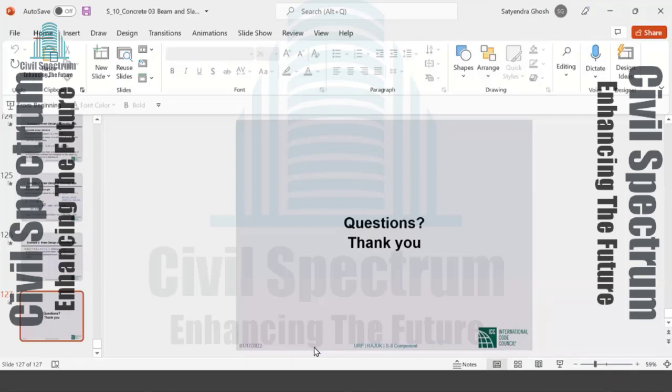Thank you, Dr. Ghosh. So is it okay to provide stirrups in closed spacing to confine the concrete, even if the shear requirement is not that much? We do that all the time. If you are in a high seismic application, the confinement requirements are so high that we end up providing, in that case, it is not stirrup. It has to be closed transverse reinforcement called hoops.